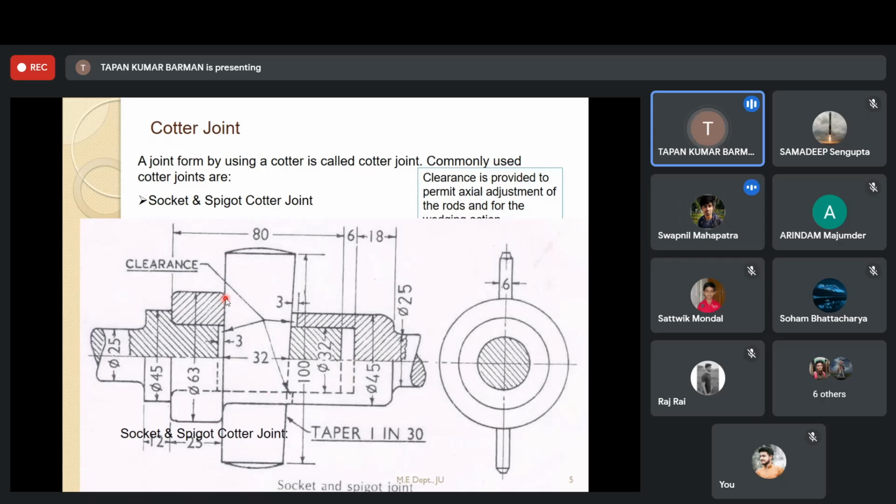Separate. Okay. So from here to here, that line should be there. From your concept, from this point to this point, since it is in section, this line can be visible. Yes, sir. But you are saying that from here to here, that line should be dotted. But the thing is, this line should be there because when we have the full component without section, then this edge can be visible. So this line is coming due to that edge of the component. Okay, that means the dotted line and the bold line are coinciding.